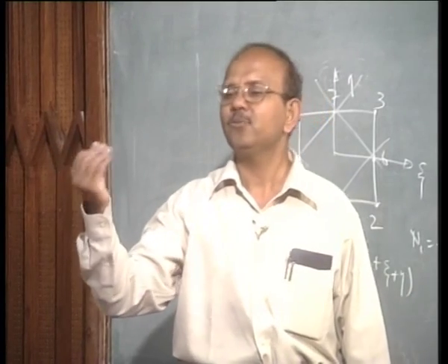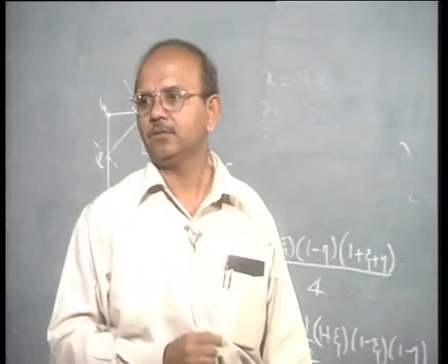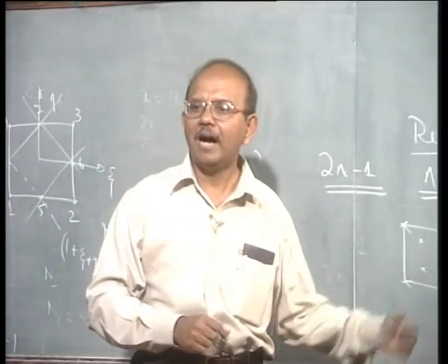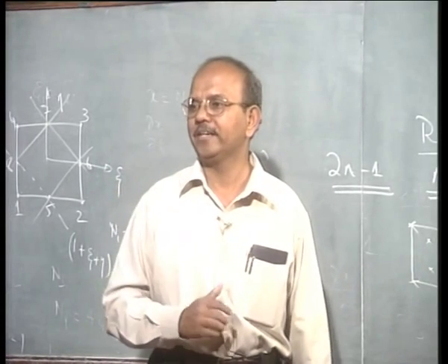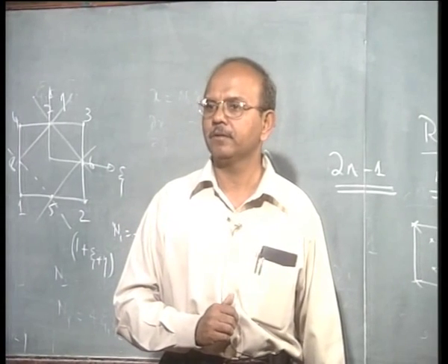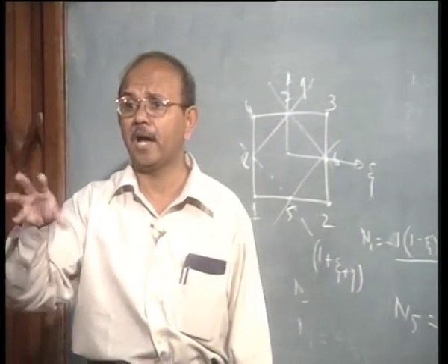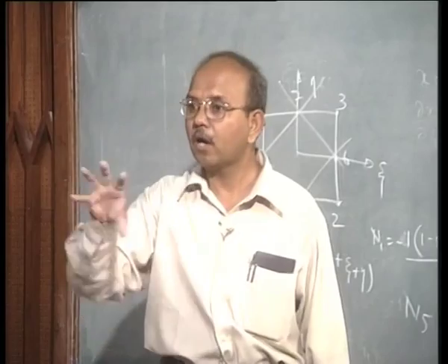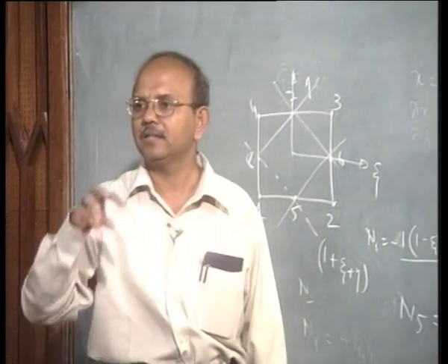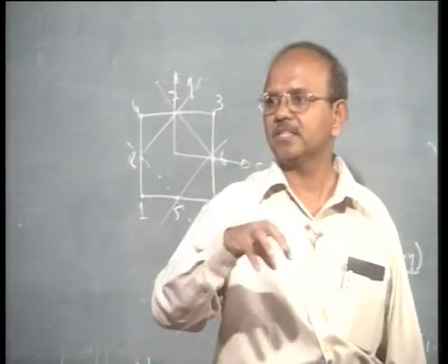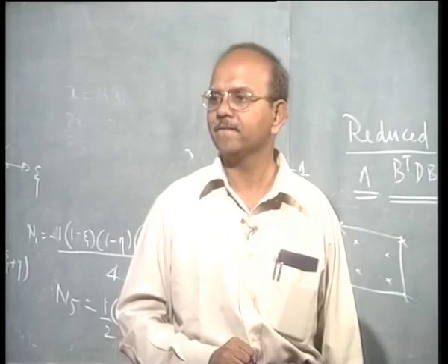Basically this is because certain higher order terms are not integrated at lower integration points, or they go to 0 at lower integration points. So some complex deformations that are introduced by higher order terms are not present when I integrate at lower integration points, because these rules are meant to integrate lower polynomials.